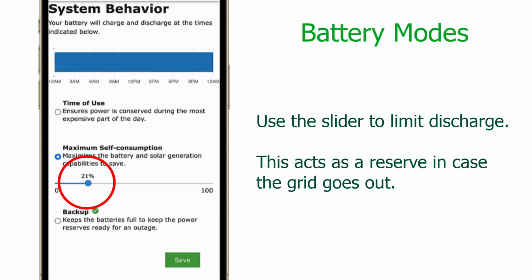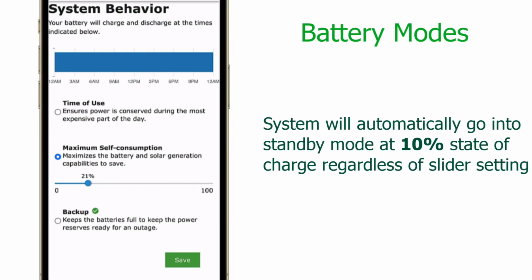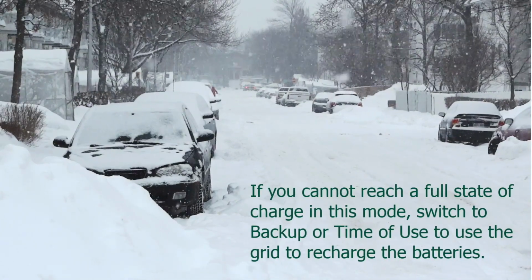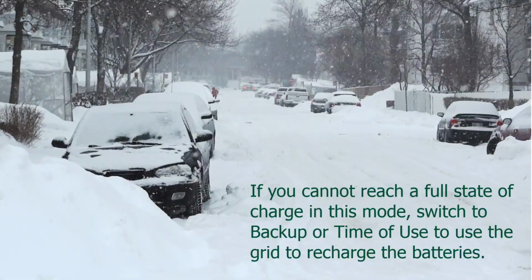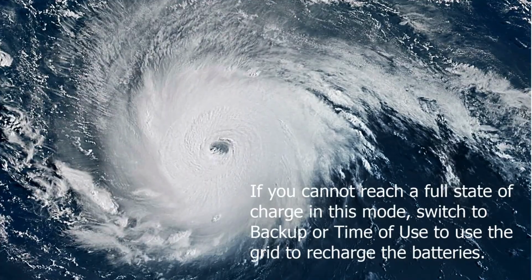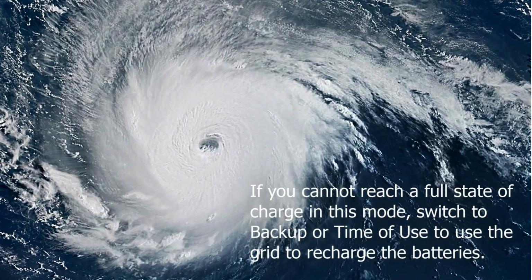This value becomes a reserve in case the grid goes down. You would then have some battery life remaining since you did not allow the batteries to discharge to the low cutoff value of 10% state of charge. If you experience periods of bad weather and cannot fully charge the batteries, you may switch to backup mode or TOU mode to use the grid to fully charge the batteries.